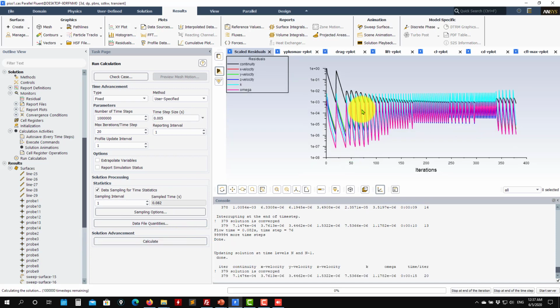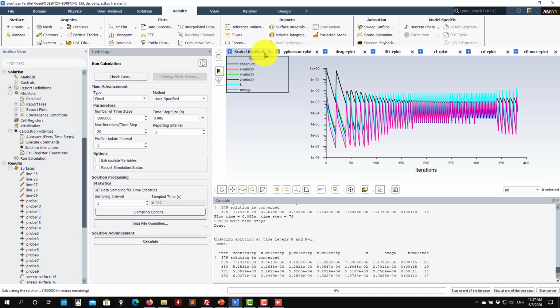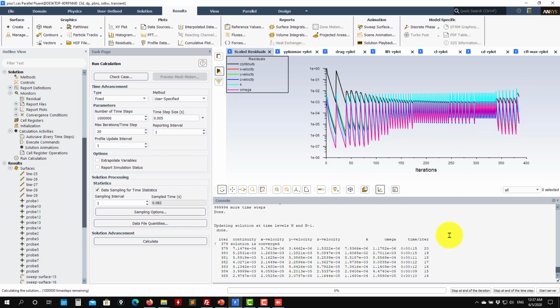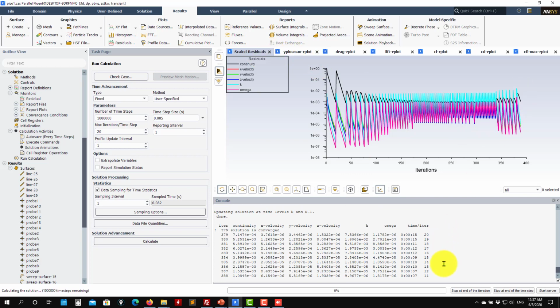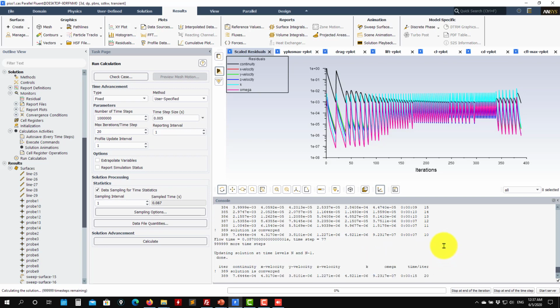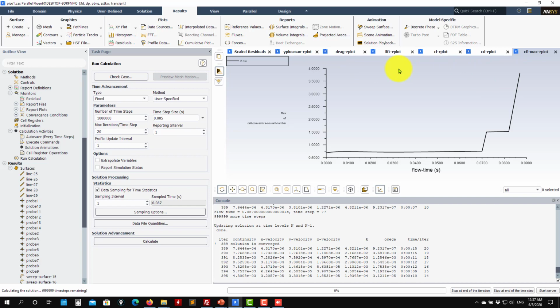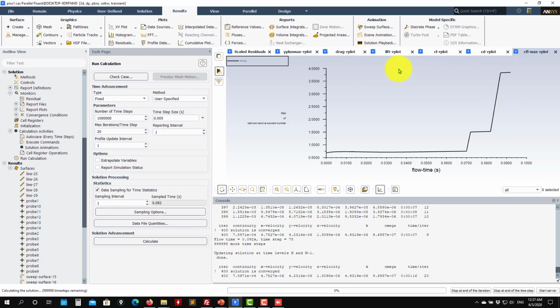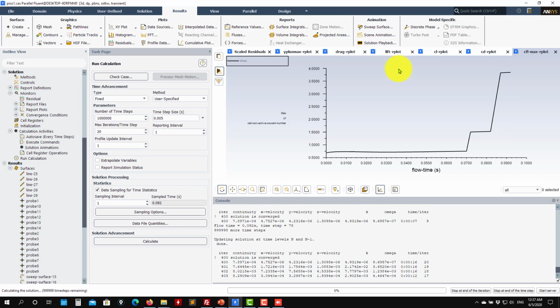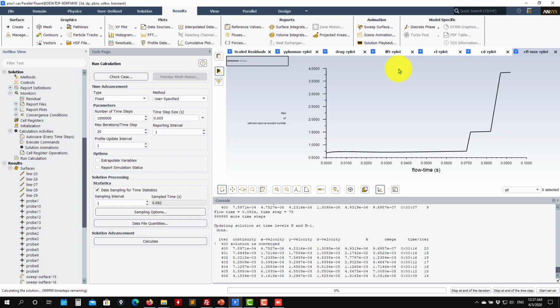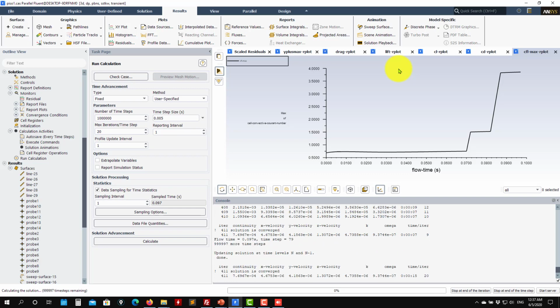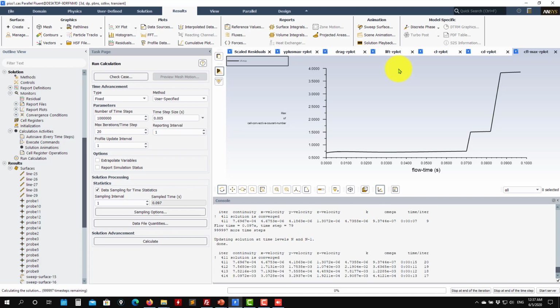faster here. Okay, again we're going to see another jump in residuals. It will take longer to converge. Probably we're almost at the limit, but see that your CFL now is larger, meaning that you will advance much faster, but it's also taking more iterations. So this is kind of a compromise. Previously you were at 0.001 taking 4 iterations. Now you are at 0.005 taking 10 iterations.